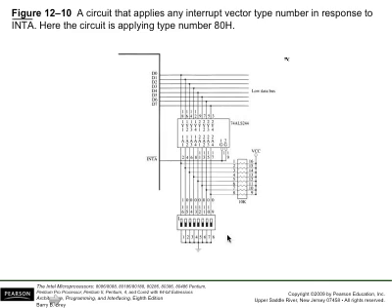These switches provide a way to connect one end of the resistors to ground. If that's the case, for example, if this switch is closed, this is going to be a logic 0. If the switch is open, this is going to be a logic 1. So with this set of switches, you can select a number, and that number will be used as the interrupt number.